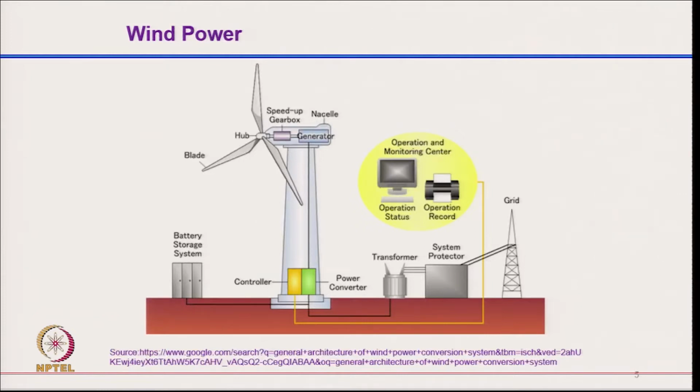And this is the typical block diagram of wind energy conversion system, where we have typically a wind turbine along with the generator on the nacelle, and of course, we normally have a gearbox, because the wind turbine runs at very low speed and many generators run at quite high speed, like a DFIG and squirrel cage induction generator. Normally they run at 1500 rpm, 1500 to 1800 rpm. So that is a 4-pole machine we adopt, and the wind turbine certainly runs typically around 50 to 150 rpm. So that is the reason.